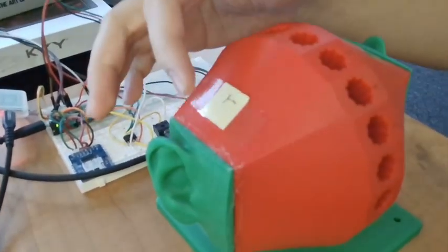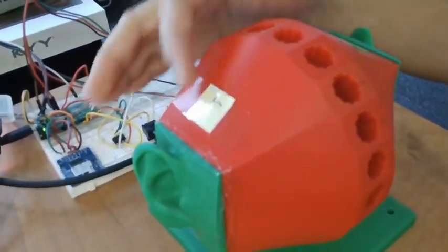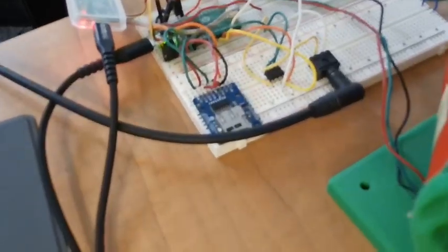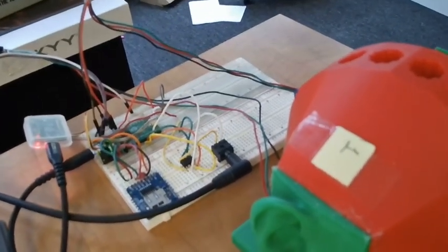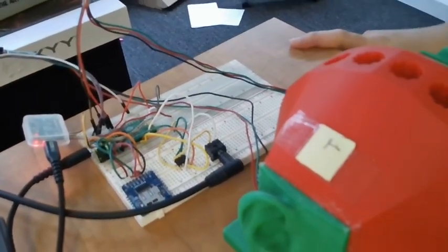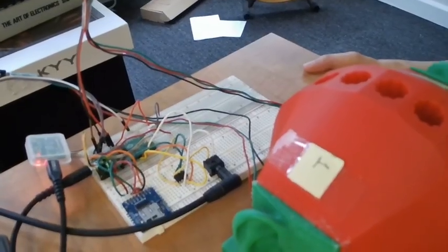Inside each of these ears is a microphone hooked up to two GPIOs, physical pins 31 and 32, which should be mapped to ADC0 and ADC1. So those are two different ADC channels. The RP2040 itself only has one ADC unit.